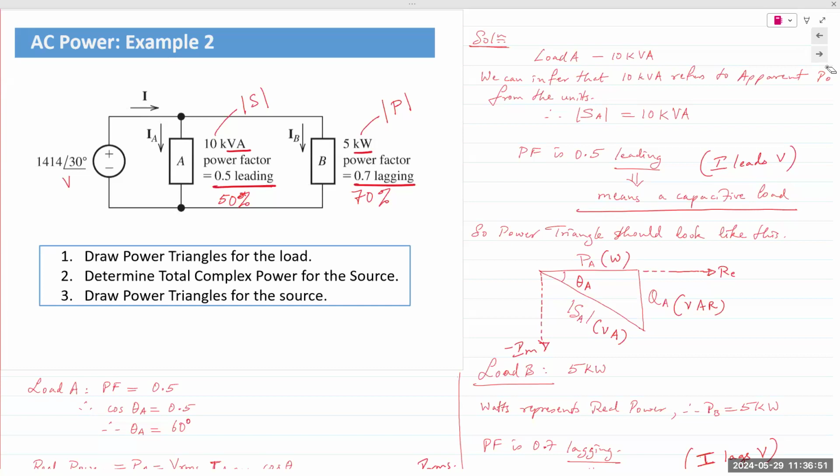Just a few minutes ago, I asked, what is our highest power factor? 1, right? If power factor is 1, what does it mean? 100%, and my angle is 0. Reactive power is completely 0. The only power in the system is the real or average power P. So if it is not 1, what does it mean? It means there is real power and there is some reactive power in the system.